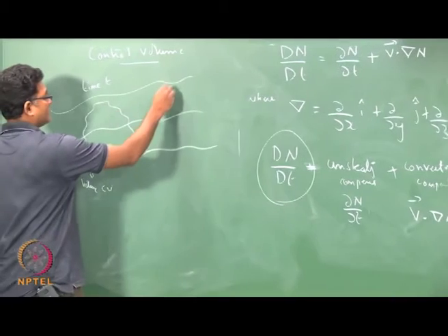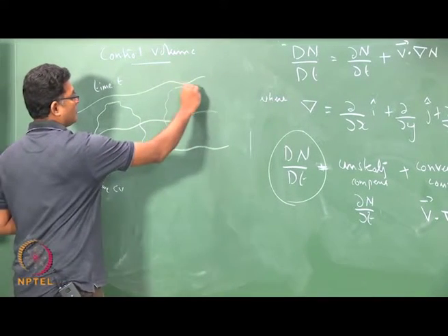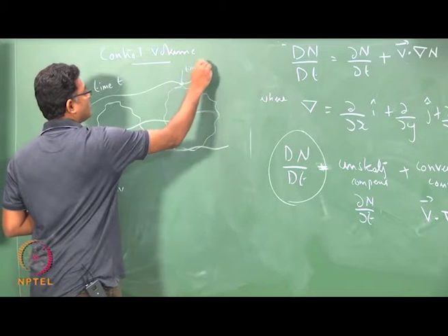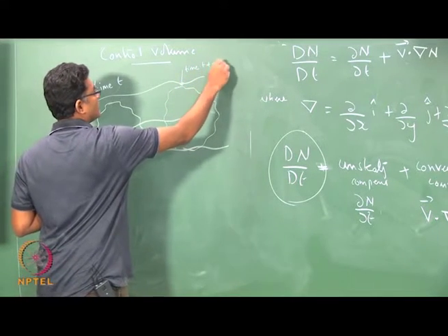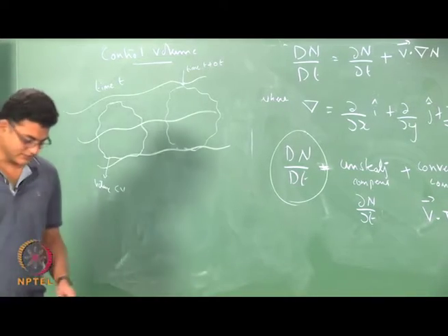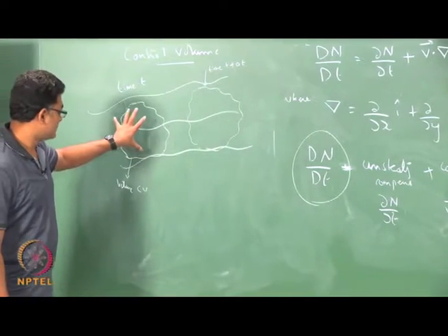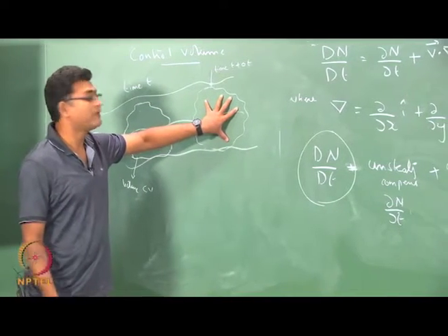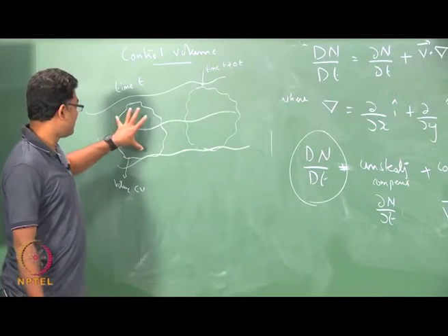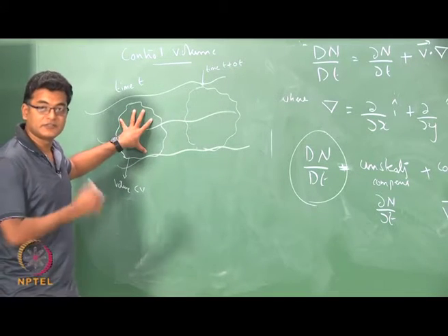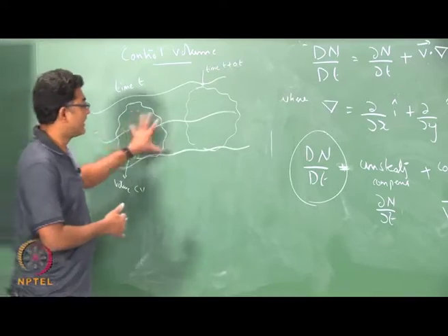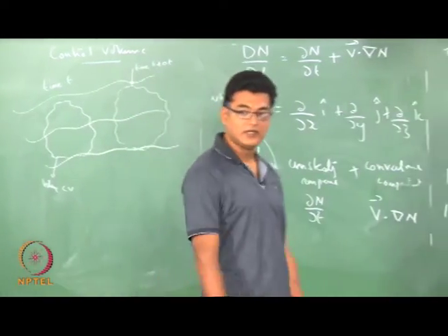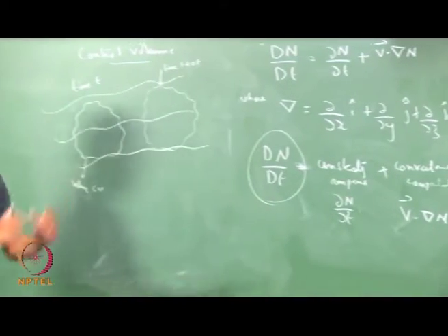Now, I consider at a different point of time what happened to the mass that is inside this particular control volume. So, this control volume changes to this particular volume at a time t plus delta t. The particles that constitute the mass are carried to this particular volume. So, the volume might have changed, but the mass is the same mass, or the particles are the same particles.